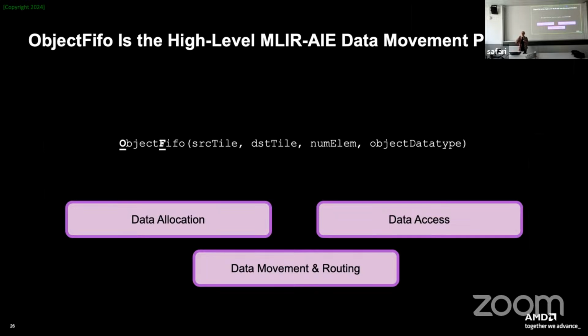The reason why we add the peer-to-peer communication, over the fact that we already connected any tile with any tile, is that we can actually offer a higher bandwidth in the peer-to-peer communication. The second reason is that there are some resources in the end that are scarce on the architecture. You only have a limited amount, that was a table we had before, of DMA channels that you can use to put data on that communication network. In some of the application examples that Gagan will show, we actually run out of DMA channels, but we can still make our implementation because we can fall back towards that high bandwidth direct peer-to-peer communication.